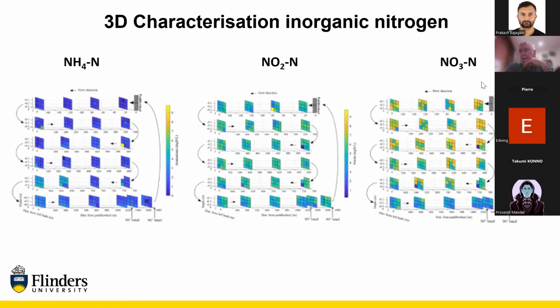What could be happening is that during the travel through the system, they start to aggregate and go into aggregates of algae and bacteria. And when you get aggregated material, you can have microclimates where on the outside of this aggregated material, flocks, where the algae and the bacteria are stuck together, you may have areas on the outside that are very aerobic, and the organisms are using a lot of oxygen. They're growing under aerobic conditions. The bacteria are oxidizing organic carbon.